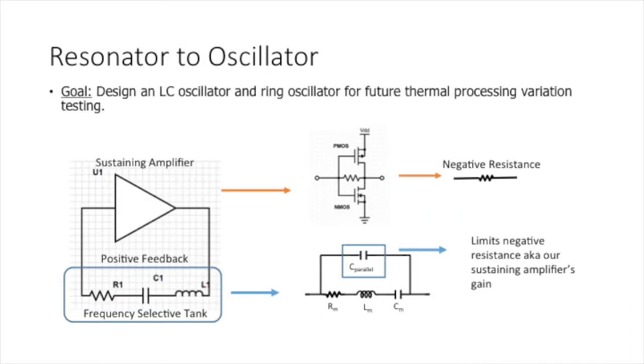Now, using the resonator, we can ideally make an oscillator with non-decaying oscillation. To do this, we would need to compensate for the losses by using a sustaining amplifier in a positive feedback. Put simply, an oscillator is built around the resonator, where the resonator selects the working frequency.